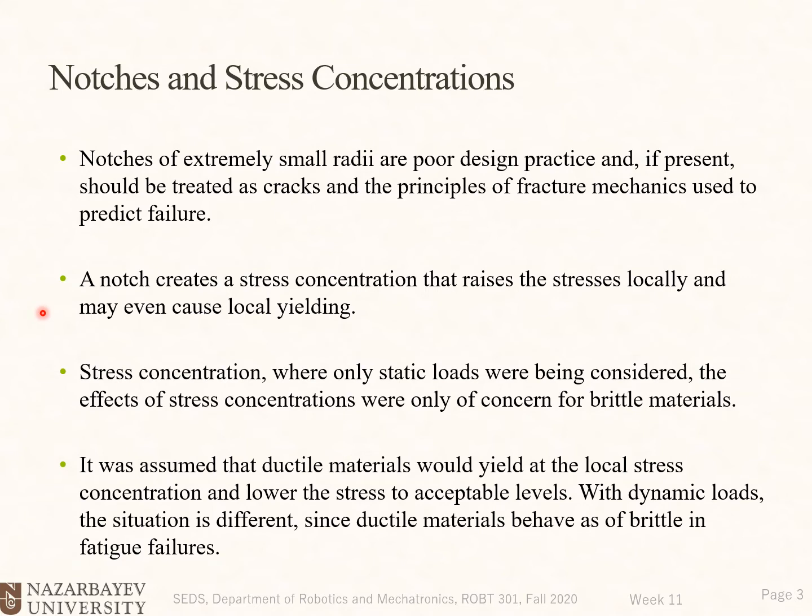A notch creates a stress concentration that raises the stresses locally and may even cause local yielding. So it's very similar to the static case. Where only static loads were being considered, the effect of a stress concentration was only of concern for brittle materials.